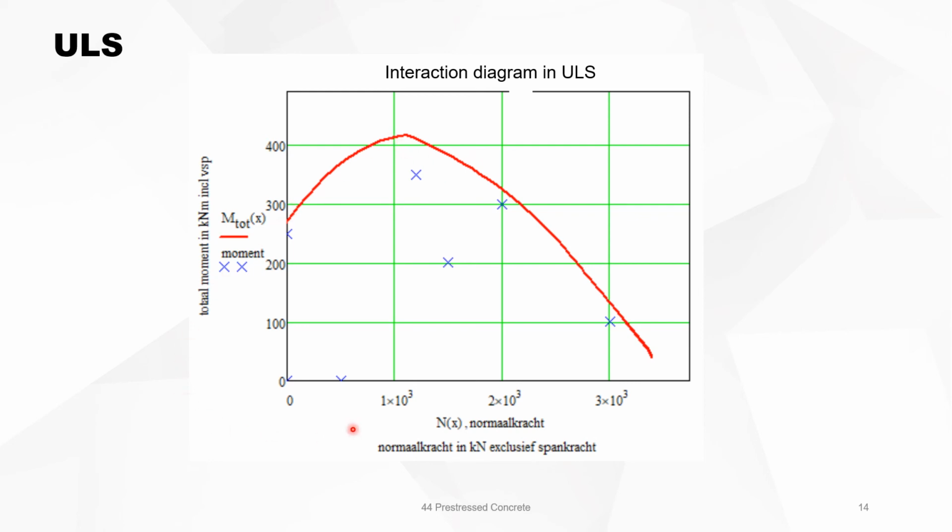And then you compare it with the forces acting on your beam, which is N_Ed, the prestressing force plus the external axial force.